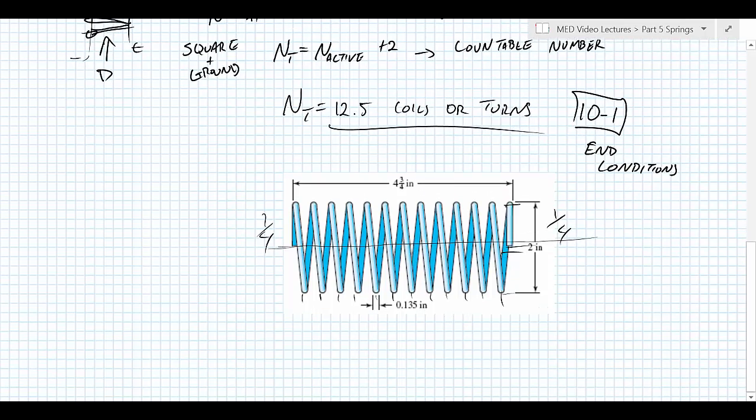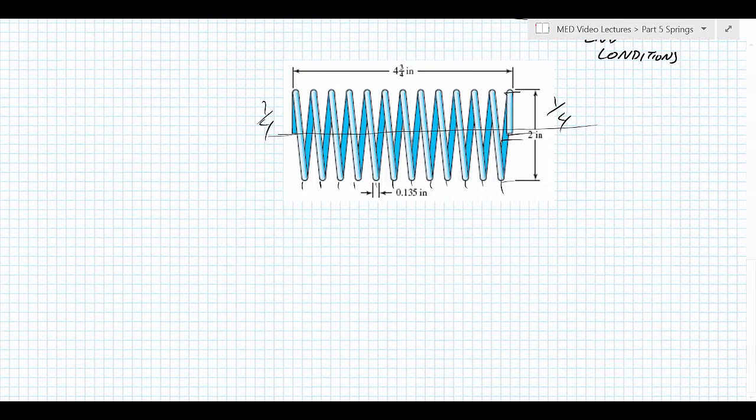All right, so if we were to apply our failure theories and think about, will a spring fail, we're going to apply stress analysis as our first step. So we can figure out forces acting on it. It should be pretty straightforward. And now we have stress. So all springs are curved beams. So that's going to cause our stress to be a little bit different than it would be otherwise.